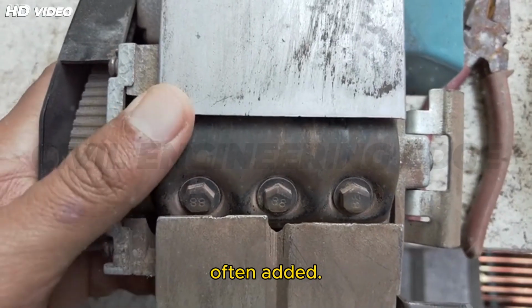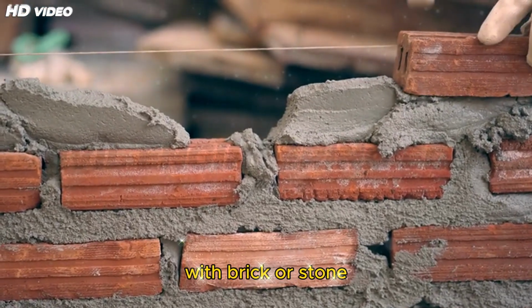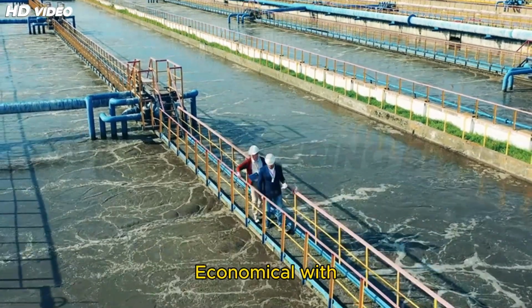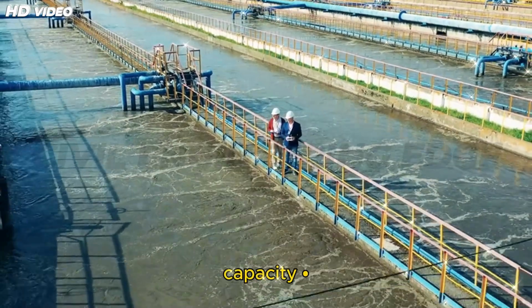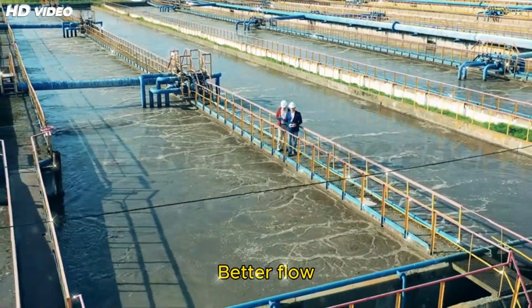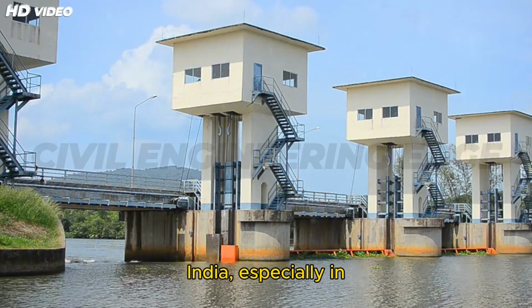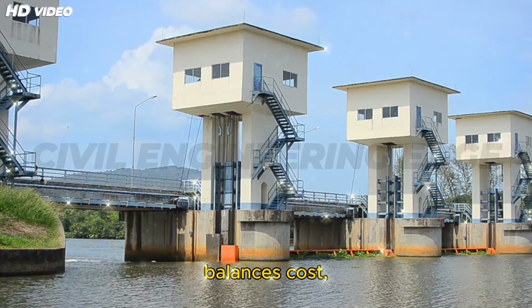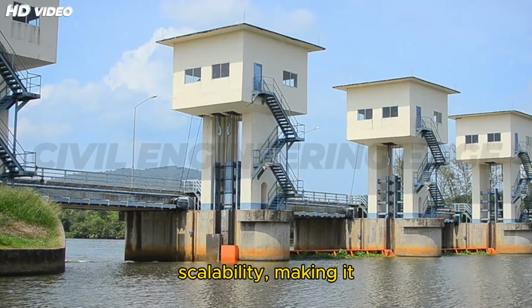Baffle blocks are often added. Materials: commonly constructed with brick or stone masonry with a concrete floor. Advantages: economical with modular construction, greater discharge capacity, better flow distribution. Widely adopted in North India, especially in the Ganga Canal system, the Sarda fall balances cost, performance, and scalability, making it ideal for main and branch canals.